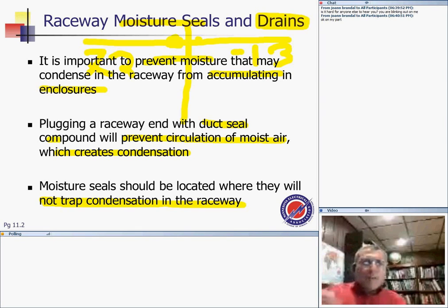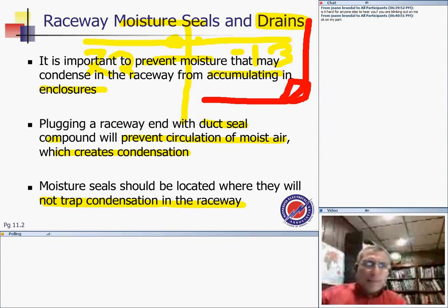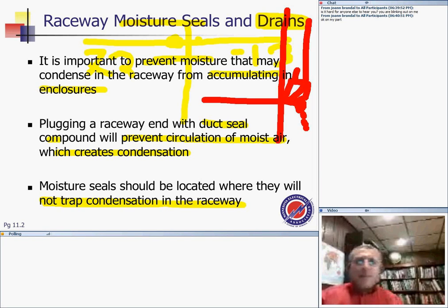Okay, so we're going to seal first, and when we put our seal, we're going to put it in a location where, coming over here, here's outside, inside, and I put my seal. These are my fittings. I'm going to make a little seal over here as I enter the building. You're going to allow a little hole here for the condensation of water. And that could be from not just in and out, guys, also from water draining into conduits coming from the top.